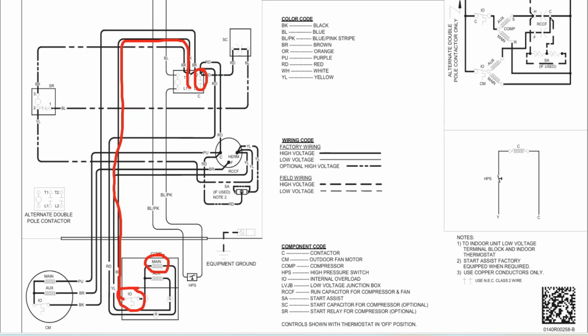Now, this is where looking at symptoms can really help you narrow down from here. So, for example, if my condenser fan motor is still running, what that tells me is that this switch on my contactor is pulled in. That switch is closed. Now, through deductive reasoning, I can kind of start narrowing down that the reason why my compressor might not be running could be due to either this switch or the winding, but it's not going to be the contactor. And you can see how this begins to help us narrow down our initial testing points to see where the problem may be.